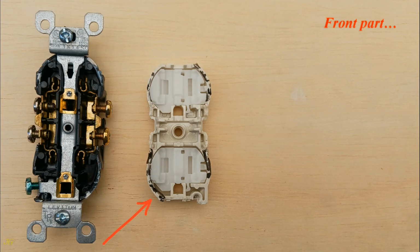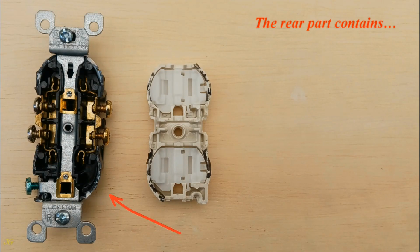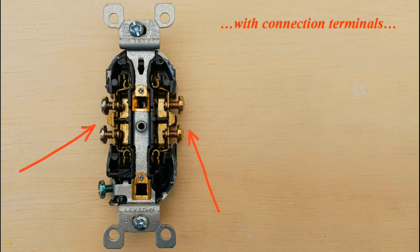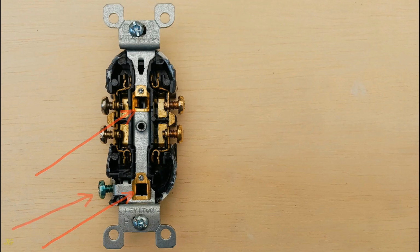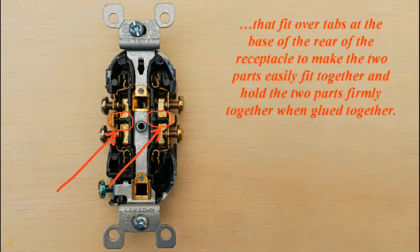Front part has safety, tamper-resistant mechanism inside its base. The rear part contains female hot contacts with connection terminals and a yoke with female ground contacts with a ground terminal. Tabs at the base of the front of the receptacle that fit over tabs at the base of the rear of the receptacle to make the two parts easily fit together and hold the two parts firmly together when glued together.